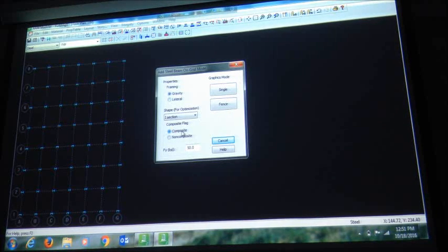And as you may have known, concrete is very good in taking compression. So in those cases, we add that concrete portion to take some compressive force on the top, and that reduces our beam size. That means it's very economical, and we want that. That whole phenomenon is called composite action. That means the beam is not only a steel beam, part of the concrete is also playing the game. It's a composition between concrete and steel. Okay?